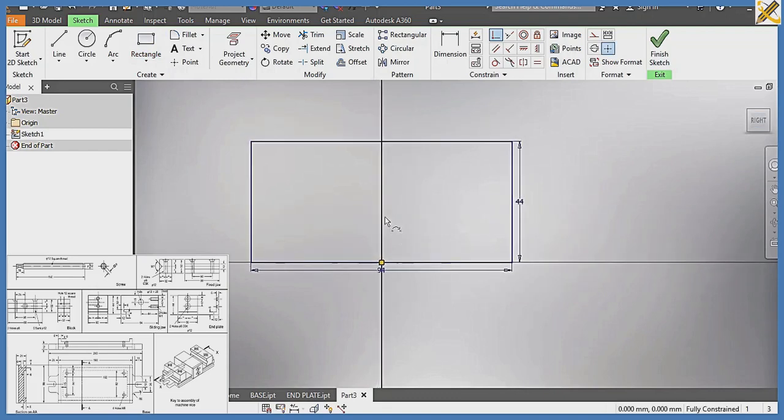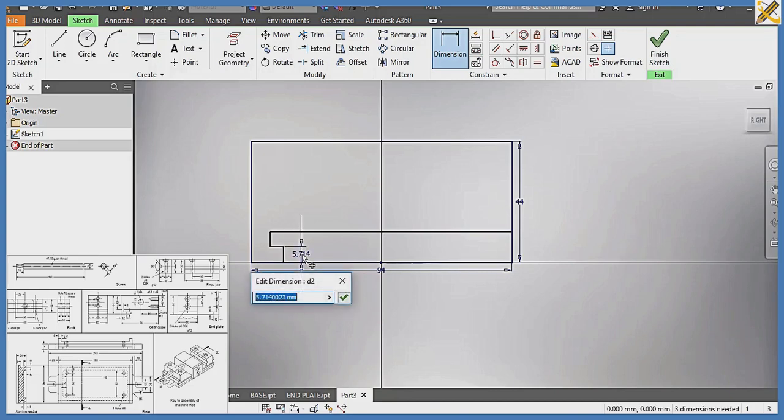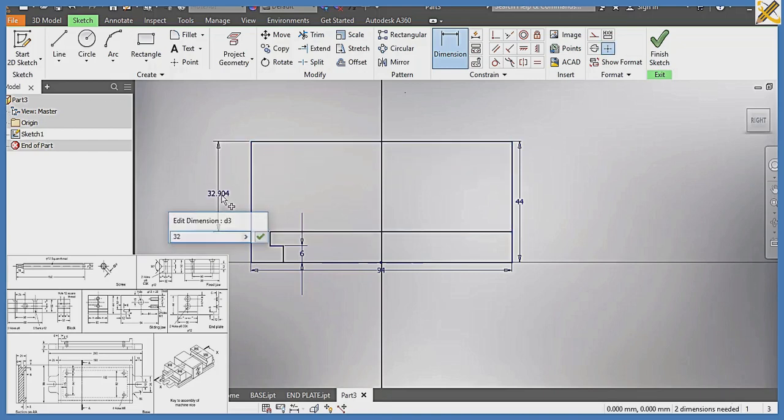All right, so what's the next thing for me to do? I'm going to pick my line, draw this, come here, go up there. Okay, I'm drawing the front view of this particular object. Then end it right here. So picking my dimension. All right, we are told that the distance here is 6, enter. Then we are also told that from here up there is 32, enter.